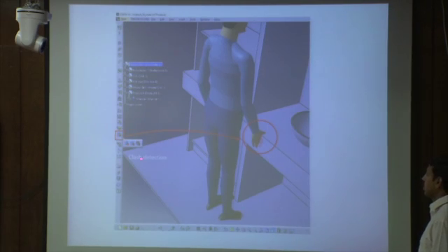There is another tool for clash detection. There are also 3-4 options: clash on, clash off, and restrict movement. This is just an example. In this example, while this hand is touching this portion of the wash basin, it is highlighted with red color circles. Then you can easily identify that this particular body segment is interfering with this particular segment of the product.